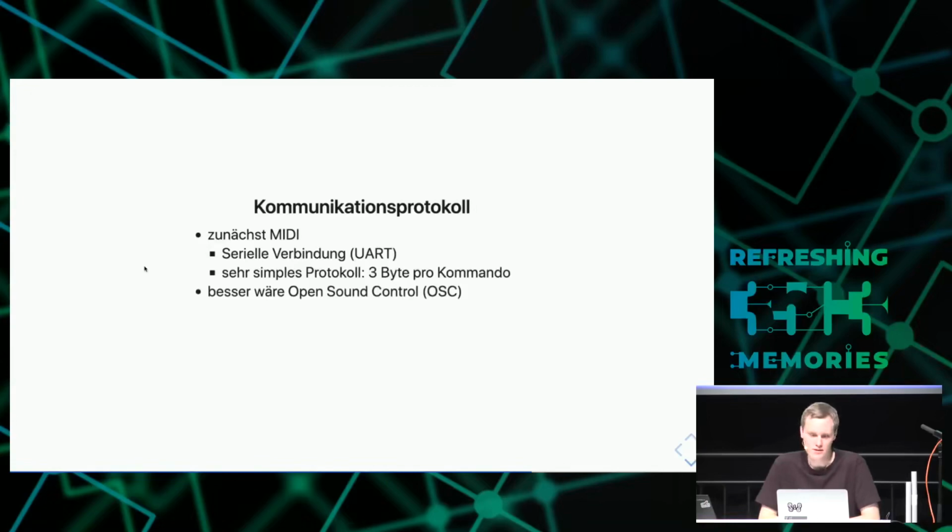So what really should be better in the future is a protocol called Open Sound Control. It's called OSC. That is network-based. You have Ethernet cables and switches, and they talk to each other using UDP packets.